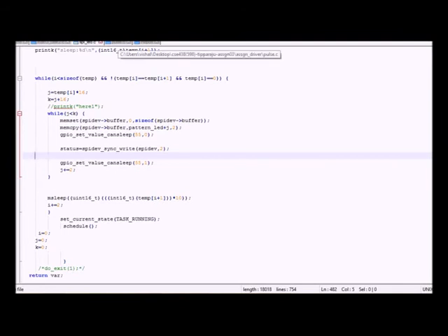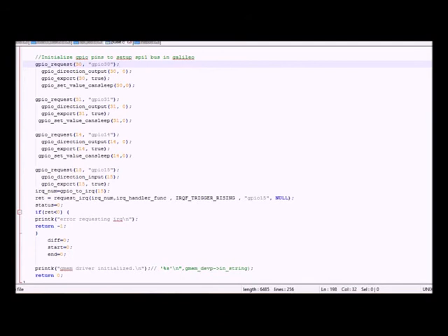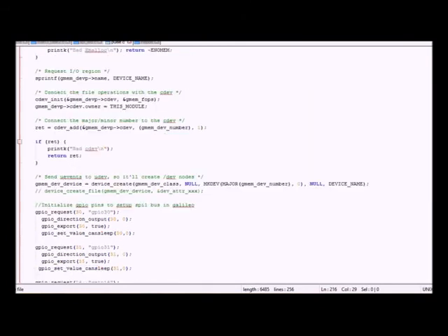Now we'll look into how we are going to handle the distance that we get from the ultrasonic sensor to handle the animation in the SPI. So if you see, we basically set our GPIO pins 30 and 31 low so that we get access to the quad GPIO pins, and then we use 14 as the trigger and 15 as the echo pin, and then we register an interrupt handler on the 15th pin so that whenever we get a rising or falling edge we generate an interrupt, and then we record the RDTSC values, which is actually more efficient in this way.